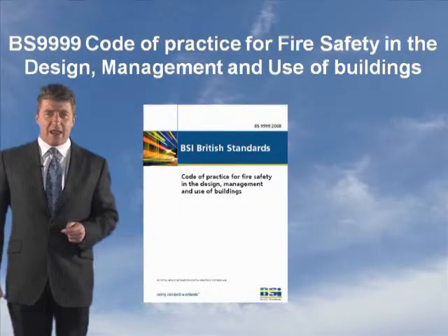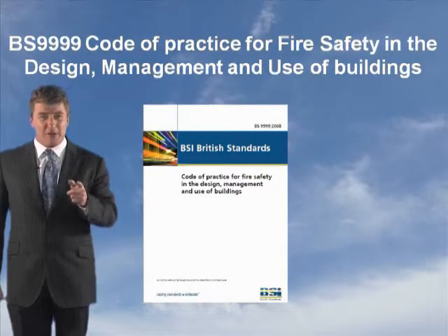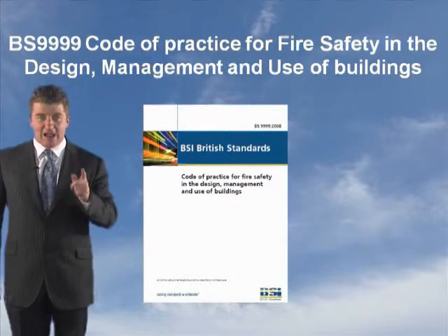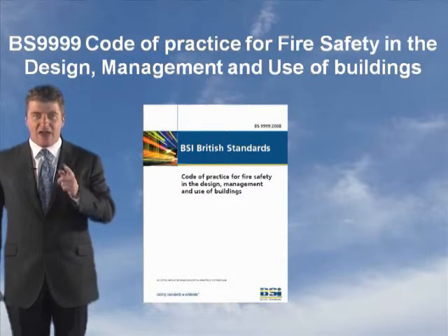Adoption of BS9999 can result in an increase in the number of people on a licence and a reduction of the required aggregate exit width of a building. If you're using ADB, you might need 8 metres of exits. If you're using BS9999 and you've got fire safety facilities in that building, like high ceilings, sprinklers and early warning, you can have 6 metres. Do you understand? That's the impact. All licensing people need to know this. They need to understand that this is very, very important in the industry. And it's without compromising life safety. What they're saying is, based on the risk profile, those people will get out.